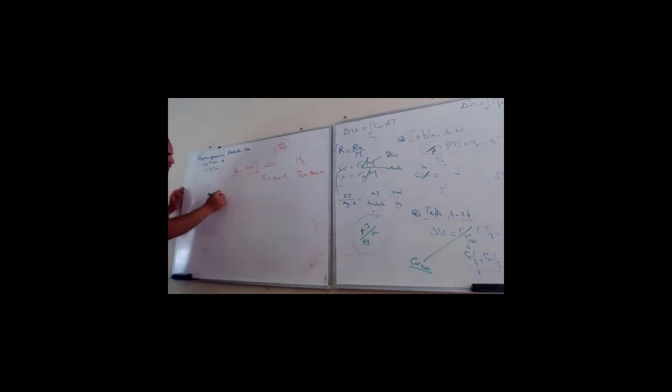The table A to C or A to B, it's in kilojoule per kilomole. You're gonna get kilojoule per kilomole. After you're done, just divide by molecular weight. That's it. You're gonna get it correctly. So what is step one? You have delta U. Let's say bar now because it's per kilomole. Integration of CV bar delta T.